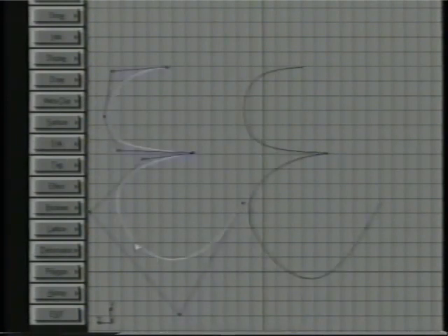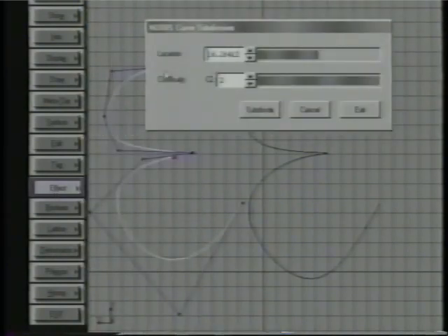Okay. Now if you use just the normal edit, add point, middle click, you can see how that changes the curve around it quite a bit. You can see I'll undo and redo that. If you use edit, add point, and NURBS curves, then you get the same thing happening. But if you use edit, or effect subdivision rather, you can see that you can add a point of any continuity. C0 or 0 would be the hard-edged, and then C1 would be a quadratic, and C2 cubic.